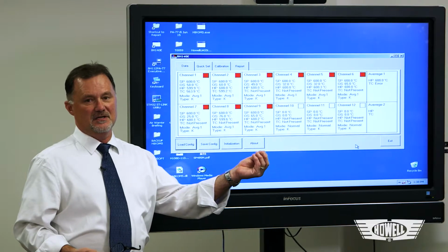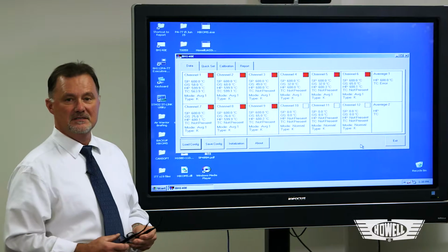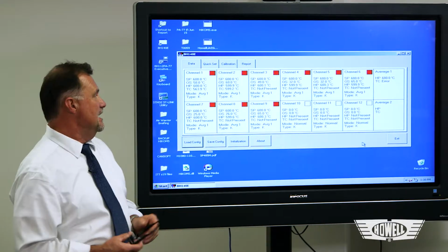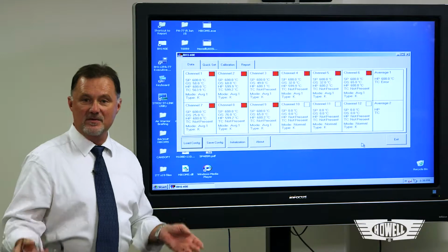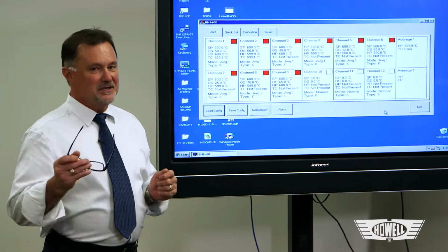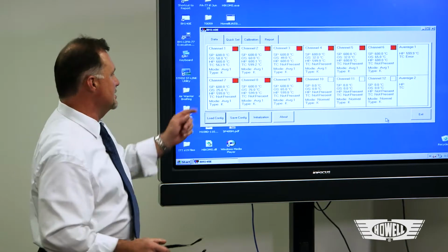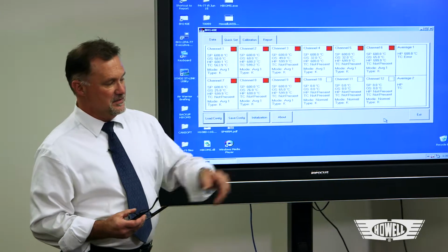Temp datum's got one temperature, TIT's got another. Pilot's wanting more temp because he's flying to temp today. He's going to end up with a lot of torque. So now he's going to be sitting there going, that engine's better than it ever has been. Let me tell you right now, engines don't get better with age. Fuel flow being consumed ought to tell you I have a thermocouple problem, and this is how it can possibly happen.